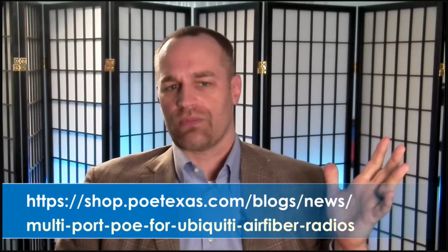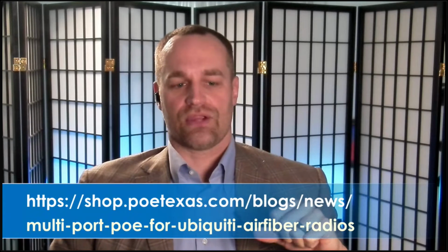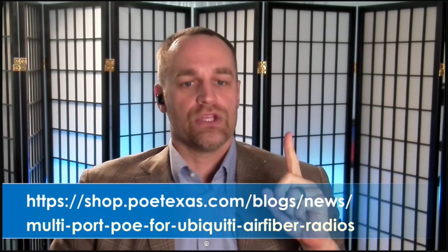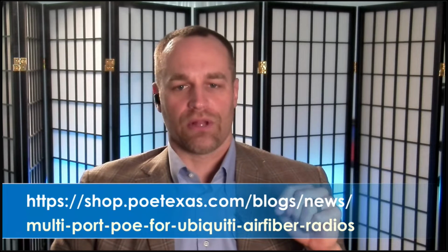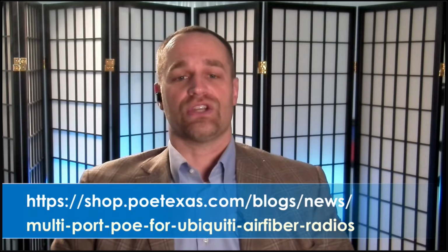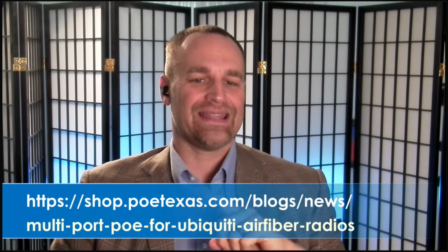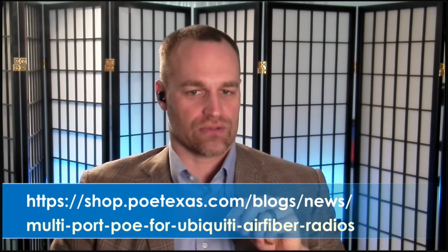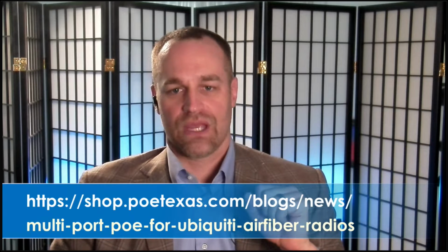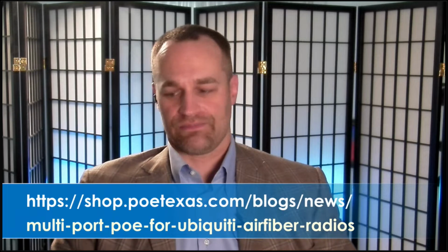What practical purpose could this have, or where do we actually see this kind of information out in the wild? You can check out one of our other popular blogs where we discovered that Ubiquiti has a relatively rare polarity change on their mode A wires, making it so that their airFibers randomly fail on anything but Ubiquiti switches and injectors. Bottom line, knowing polarity and mode can save you some real headaches when it comes to building a PoE system.